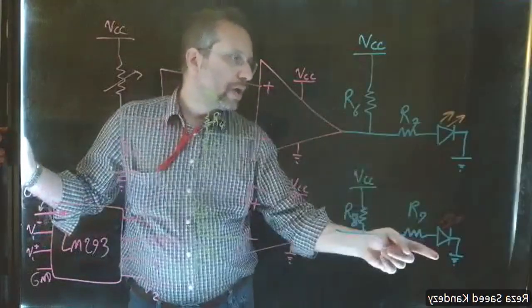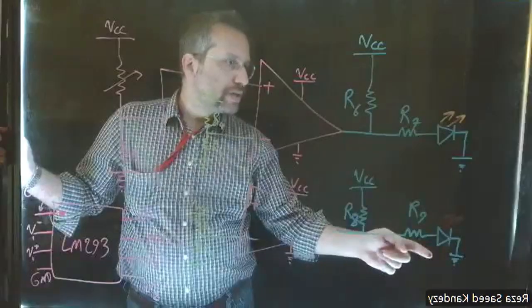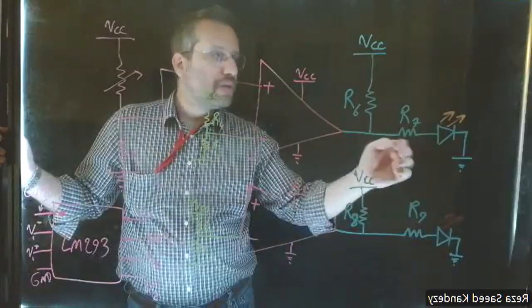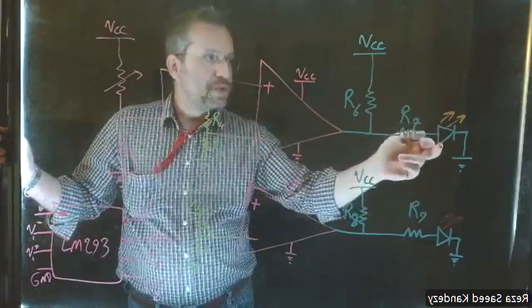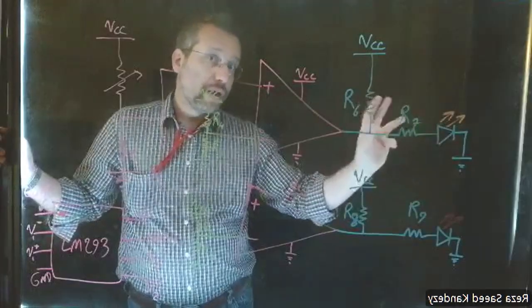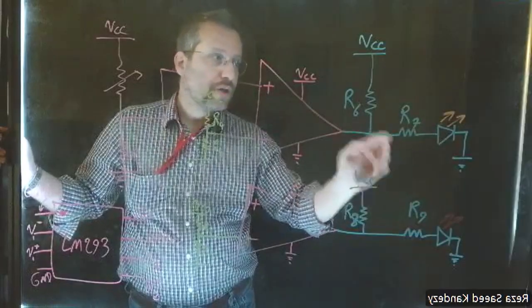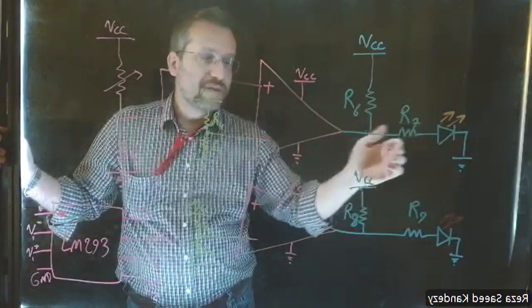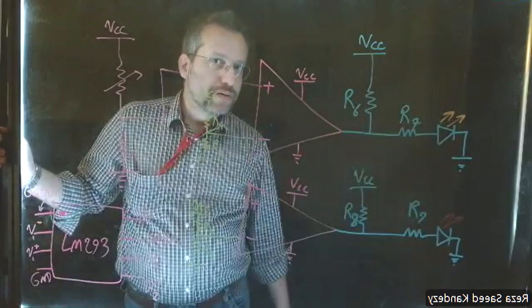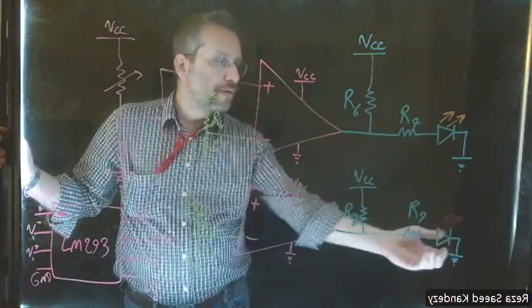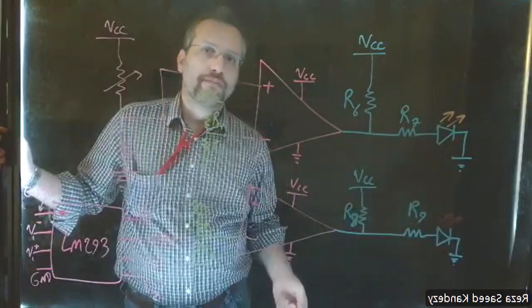And then we have our LEDs. If we have a high value, meaning we have a legitimate amount of current, the LED will be turned on, and we define that by this resistor. This is the current limiter. You have to also design the value for that. Same goes for the other LED. If we have a relatively high level of current, this one will turn on.